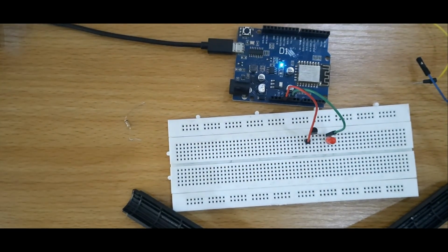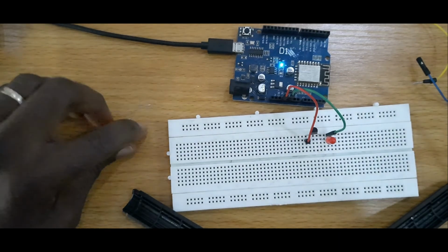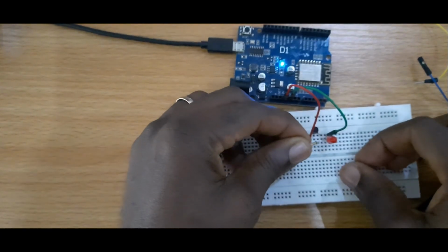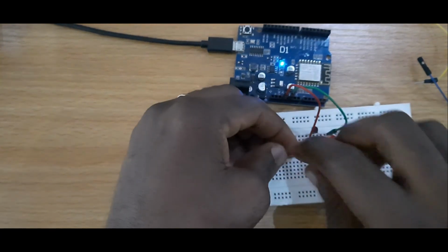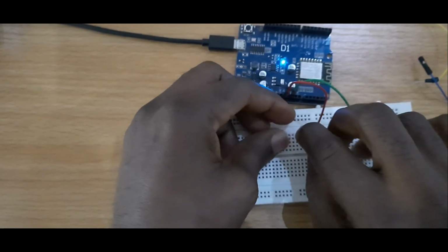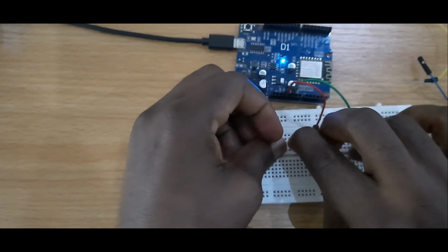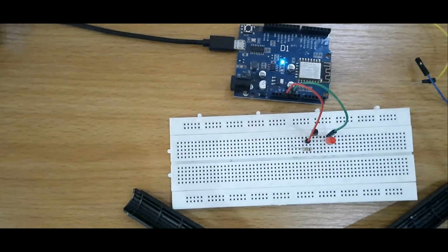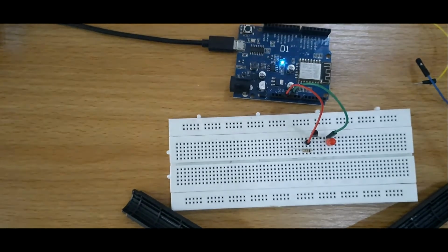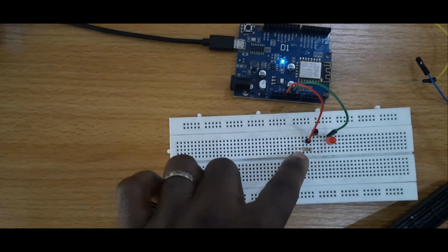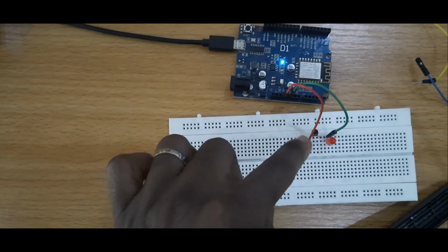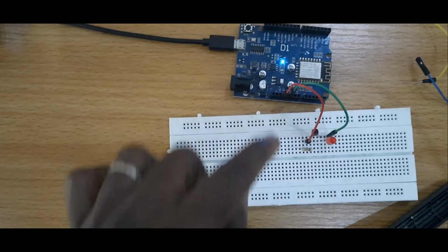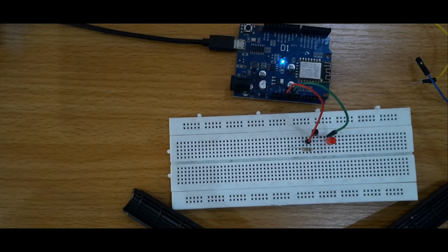Now this is the time for the trigger to do the work. I like to connect my resistor first. So I have the resistor connected to the base, the midpoint. Remember the middle? That's the base, and that's the reason why we're calculating all this. This is the main part of the task. So I've connected my resistor firmly in the breadboard. You can see I have my resistor connected to the base, the midpoint. I have the 3.3 volts connected to the 3.3 volt pin on the Arduino. We are working with 3.3 volt logic.